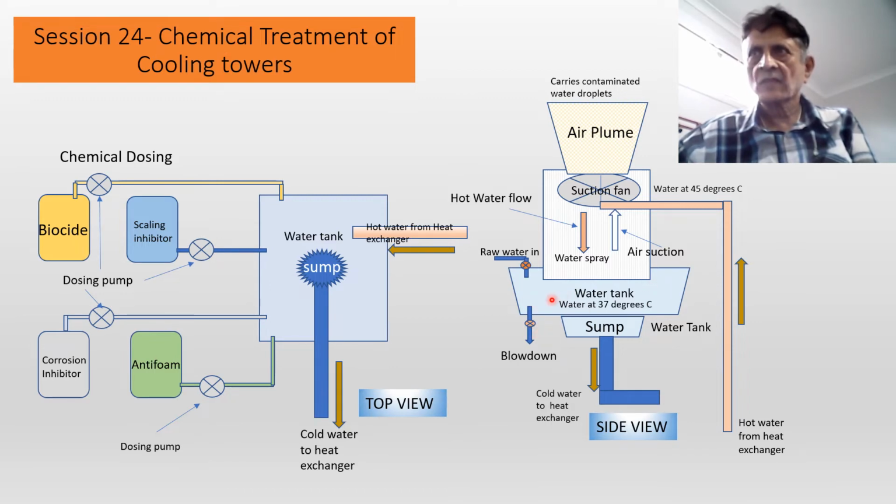When the water gets to a TDS of 2000, 2200, etc., the blowdown valve opens to allow a significant amount of water to drain out, and it is topped up by raw water. Obviously, when this happens, the TDS will drop, but the chemicals are also wasted through the blowdown. So chemicals have to be added every time there is a blowdown.